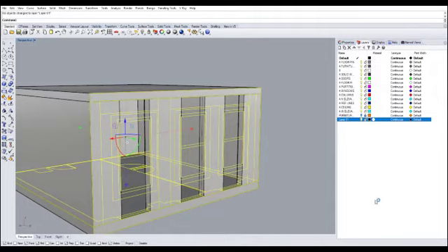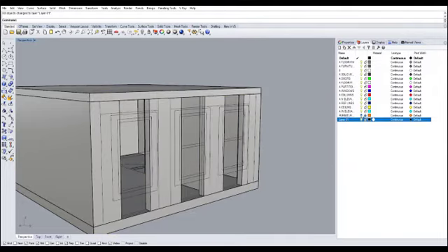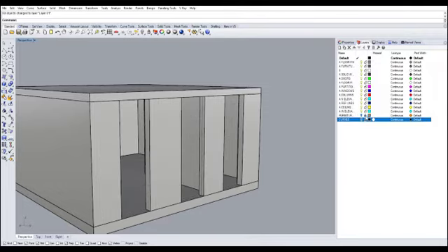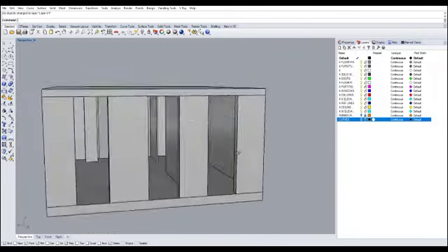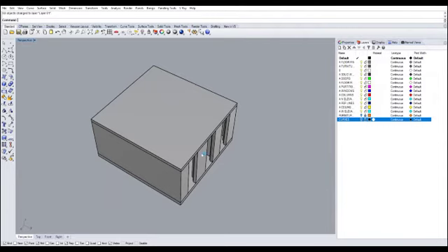Change object layer. Now that it's been moved there, we can double check by clicking on and off, and there you have it. All our curves are there. Let's rename this layer curves. Let's also hide it and lock it. Now this is almost ready to go.